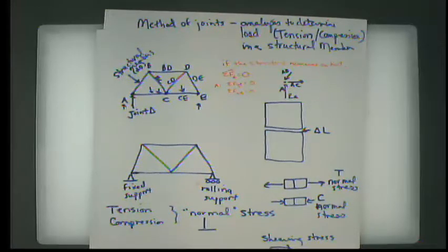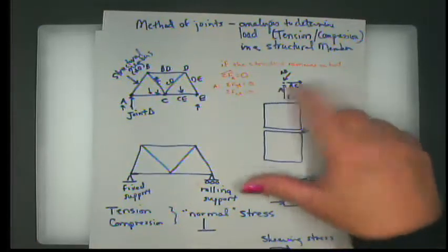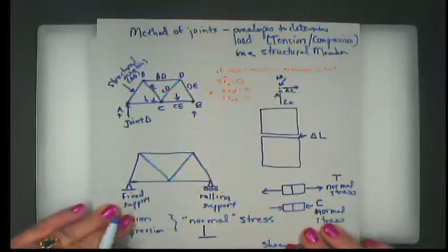So that means the angular relationship of the truss is also the angular relationship of the forces. When we do a free body diagram of the forces going into A, we can use the angles of the truss itself to show us what the angles will be going in and going out. And they have to sum to 0 at A.